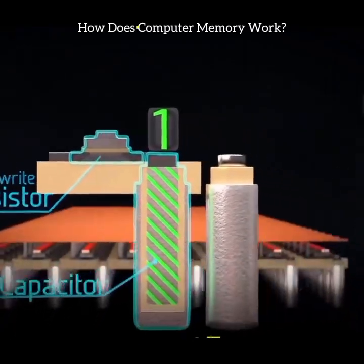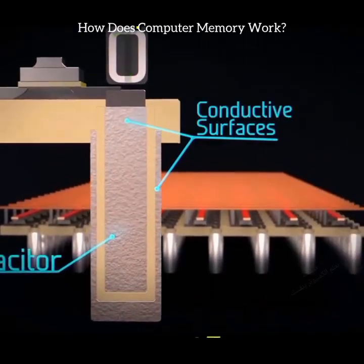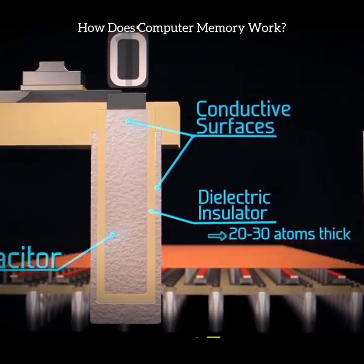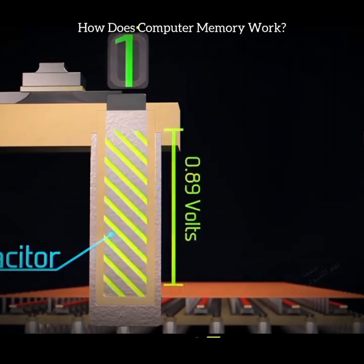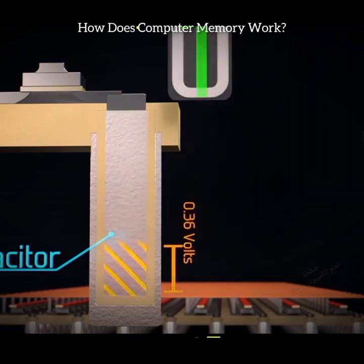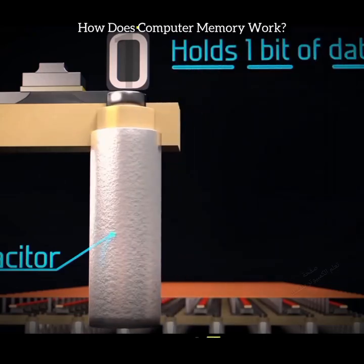The capacitor is shaped like a deep trench dug into silicon and is composed of two conductive surfaces separated by a dielectric insulator or barrier just a few atoms thick, which stops the flow of electrons but allows electric fields to pass through. If this capacitor is charged up with electrons to 1 volt, it's a binary 1. And if no charges are present, and it's at 0 volts, it's a binary 0. And thus, this cell only holds 1 bit of data.